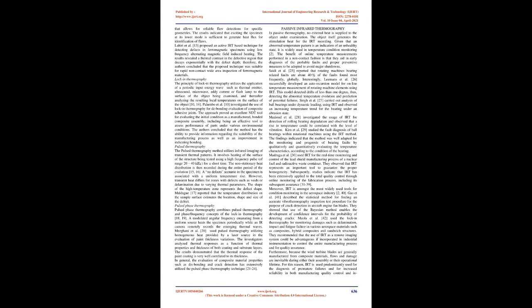10, 14. Palumbo et al. investigated the use of lock-in thermography for debonding evaluation of composite adhesive joints. The approach proved an excellent NDT tool for evaluating the initial condition of a manufactured, bonded composite assembly, including being an effective tool to assess performance of parts under various environmental conditions. The authors concluded that the method has the ability to provide information regarding the suitability of the manufacturing process as well as an improvement in indicating bonding.